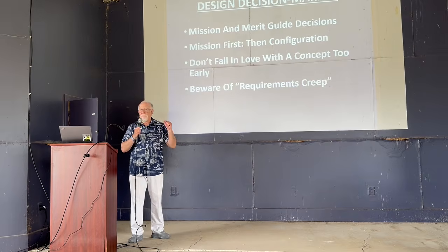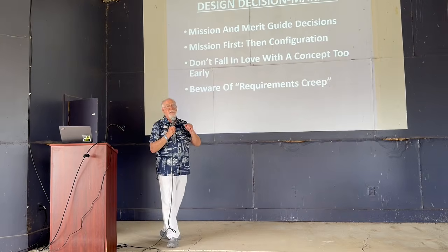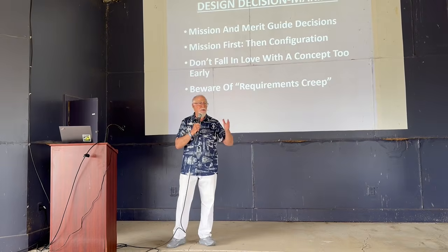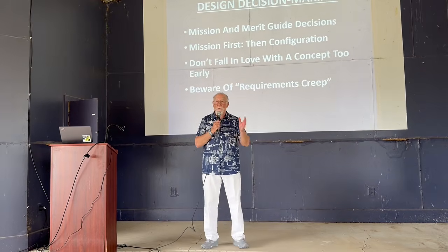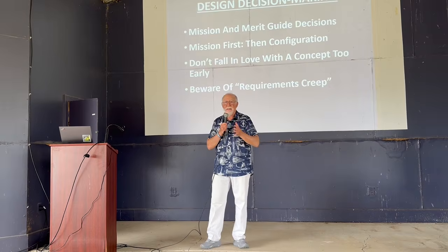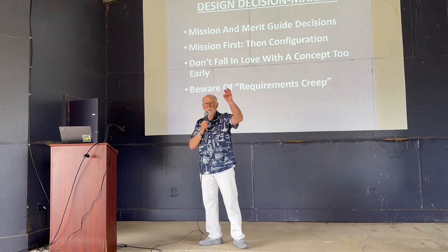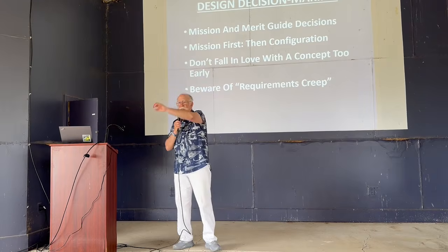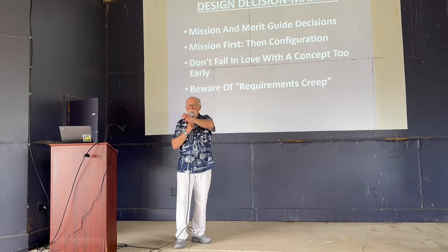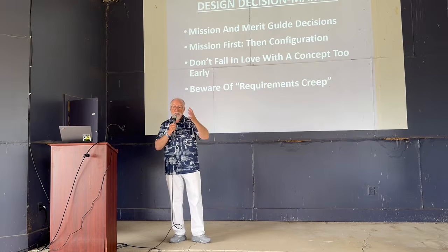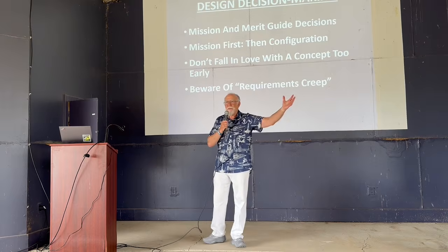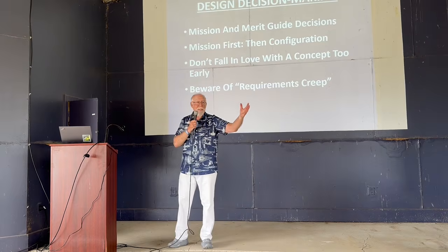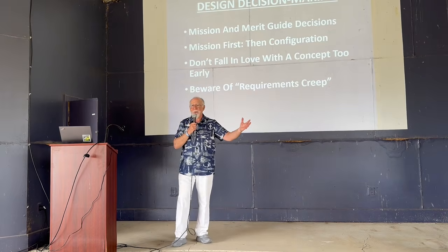Mission first, then configuration. A very common mistake. If you've been around as long as I have, you've seen multiple fad configurations. Sometimes they're actually good for one or another mission. Sometimes they're not a bad idea, but they're not the universal solution for everything. And if you fall in love with a configuration first and then try to force it into a mission, you're liable to end up with a badly compromised airplane. There are some missions for which something really cool, exotic, and innovative is the right way to go. And you have only to look at the STOL world to realize there are some places where a good old-fashioned high-wing, strut-braced, fabric-covered airplane is the right way to go.